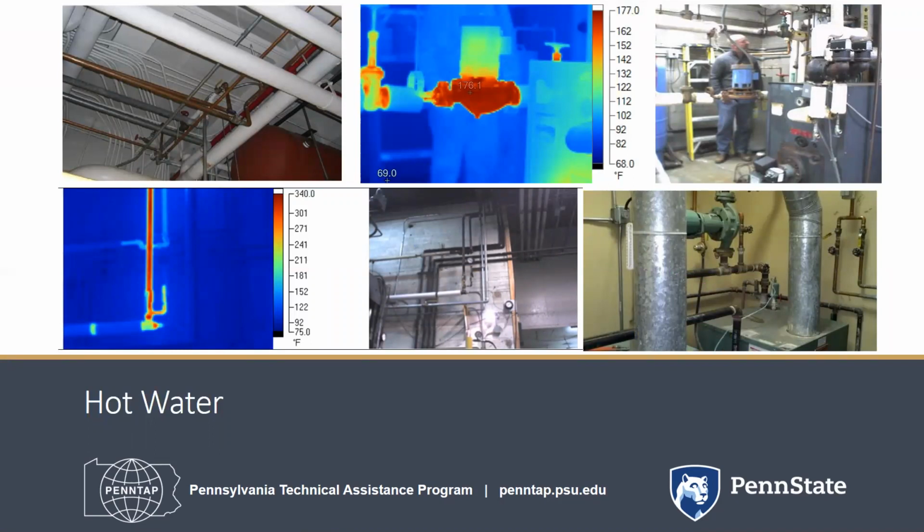Let's talk a little bit now about the hot water systems. You may use hot water for space heating and, of course, for your domestic hot water. For heating, you want to insulate the tanks and feed lines. Look for leaks, external and internal. For example, internal can be found in steam traps. Look for those loose or missing insulation pieces. See if you have a high stack temperature.